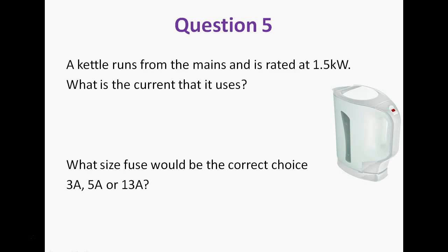Well, let's deal with the first part. This type of question can sometimes confuse people because it doesn't give the voltage, but remembering mains voltage, use 230 volts. And here also we've got another banana skin, in that the kettle is rated at 1.5 kilowatts, remembering that kilo anything is 1000. So that means 1000 watts. So if kilo is 1000, the kettle is rated at 1500 watts.